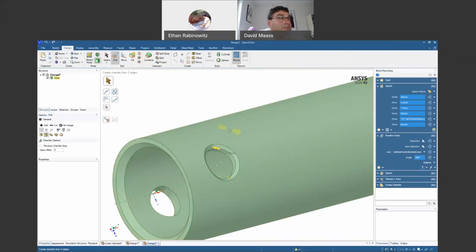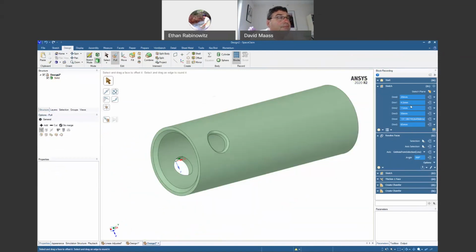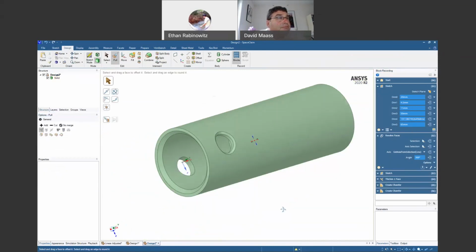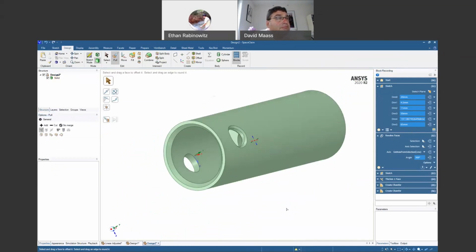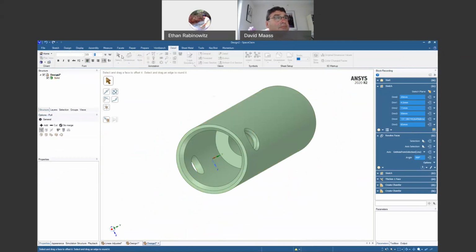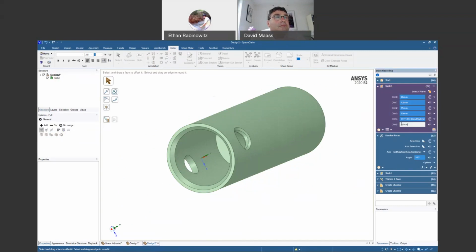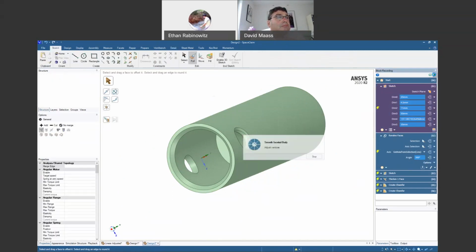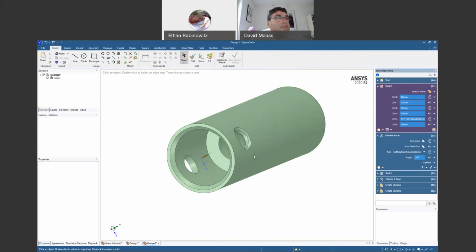and then let's say I want to go back and change something at the beginning. Normally, if I want to change where this face is, I have to select it, pull on it, set up a dimension, or do the same thing with this dimension tool here. But what this now allows me to do is, if I know the dimension value I want, I simply update it in this panel, click play, and it repeats every action that happened after that, even when the actions happen on that face.